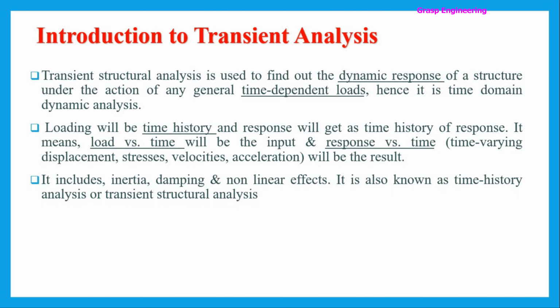In this case, the loading will be a time history and you will also get a time history response. So in simple words, you apply load versus time as an input and you get output in the form of response versus time. It might be displacement versus time, stresses versus time, velocity, accelerations.